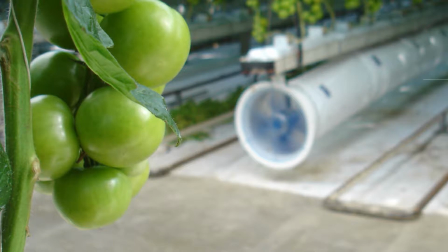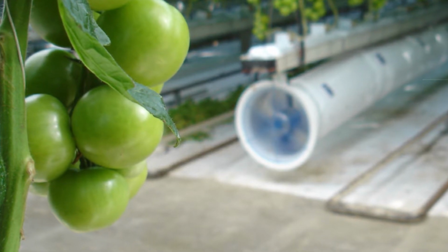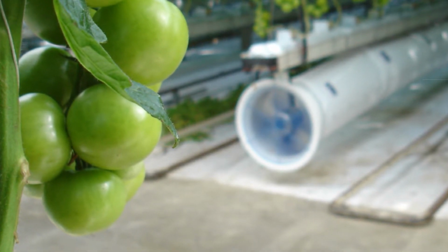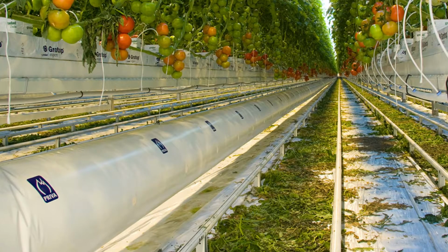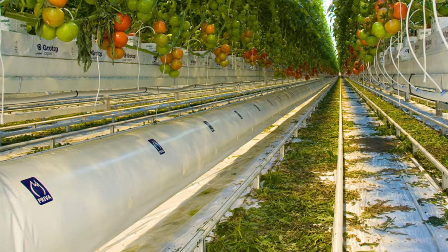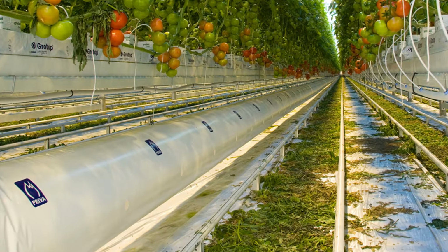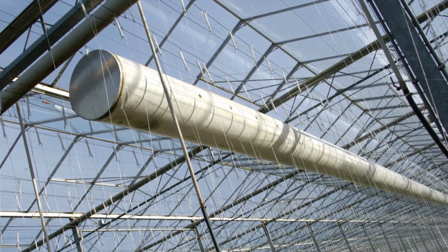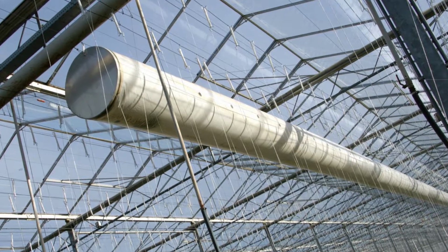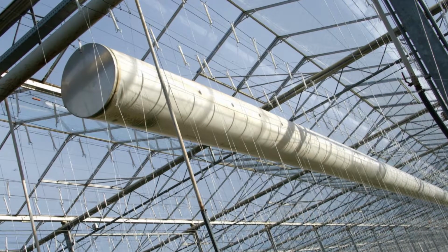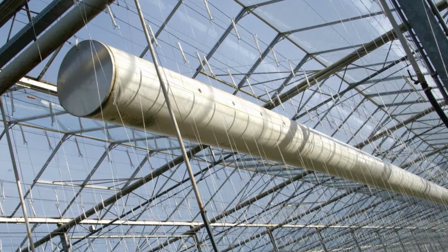Another option is to use long plastic tubes, incorporating a fan underneath the crop. The tubes have holes along their length, allowing air to escape, resulting in some air movement around the tubes. However, the nature of the design usually means a fan at one end of the tube, which can lead to unevenness in airflow horizontally out of the perforations in the tube.